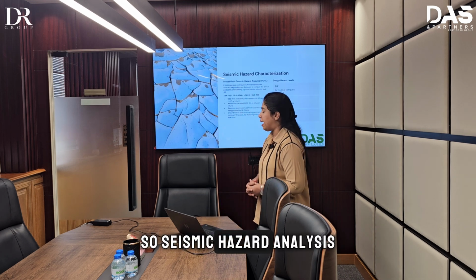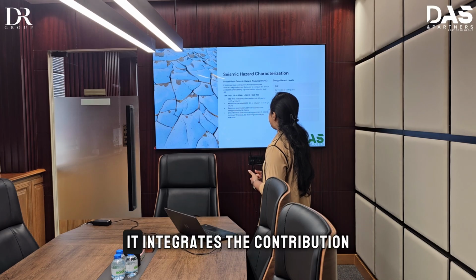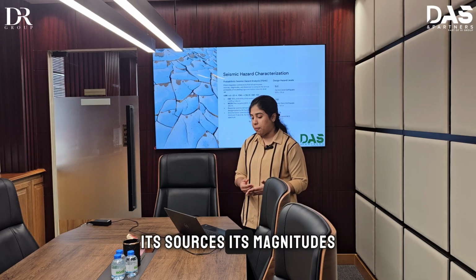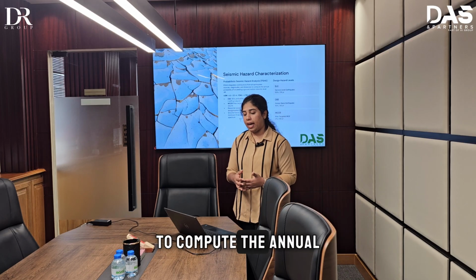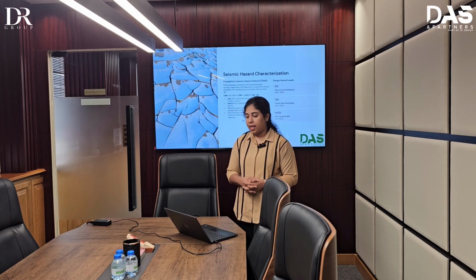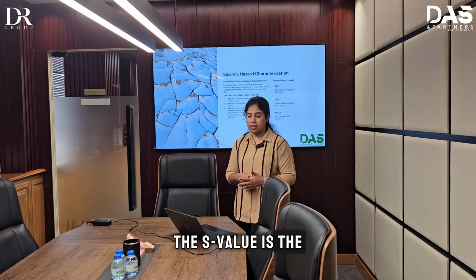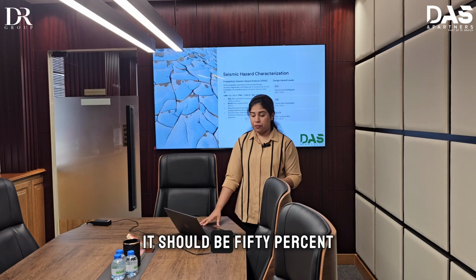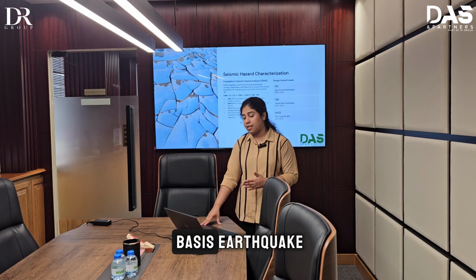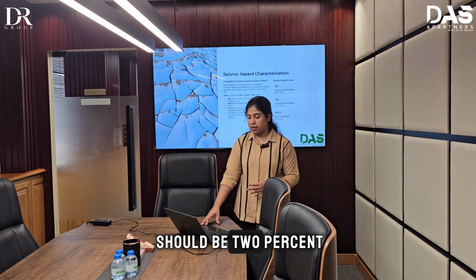Seismic hazard categorization. The probabilistic seismic hazard analysis integrates the contribution from all earthquake sources, magnitudes and distances to compute the annual probability of exceeding a ground motion intensity level. The design hazard levels are of different types. The SLE, the service level earthquake, is 50%. The DBE, the design basis earthquake, is 10%, and the risk-targeted MCE is 2%.